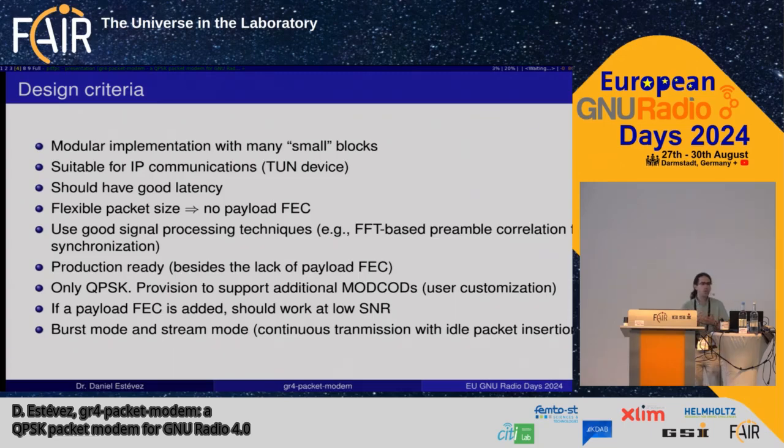And the modem should also support in the transmitter 2 different modes, which are burst mode. That's when I have 1 packet to send, I send it. If I don't have anything to send, radio silence. And also stream mode, which basically emulates how DVB-S2 and similar protocols work, which is whenever I have a packet to send, I send it. Whenever I have nothing, I keep my carrier, I keep my transmission, I keep sending idle frames. And that introduces considerations for latency.